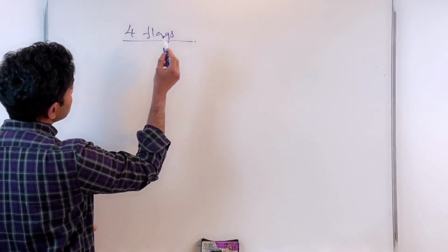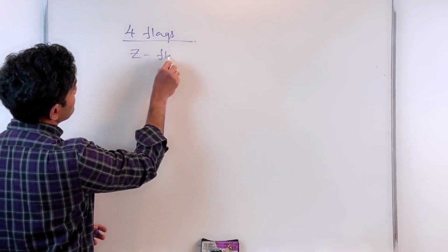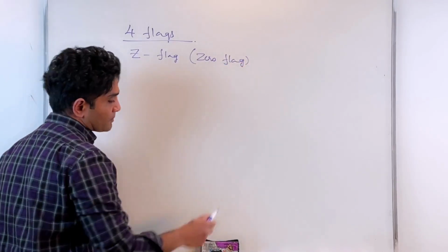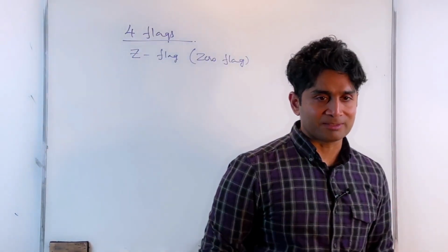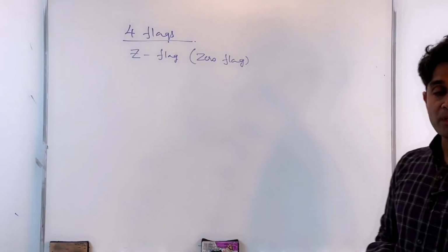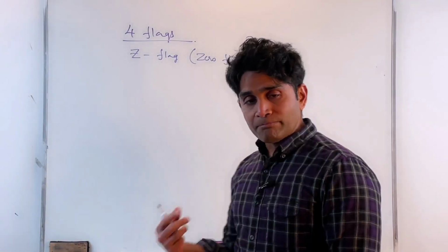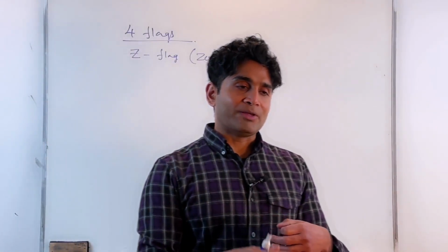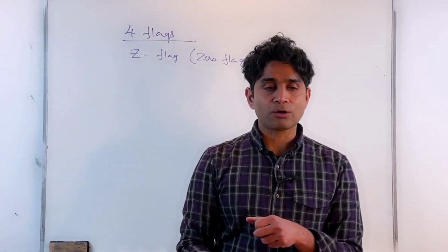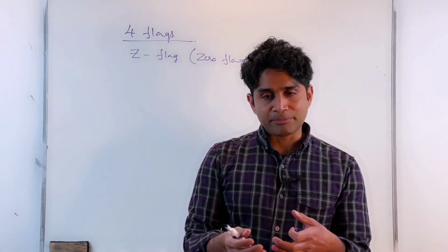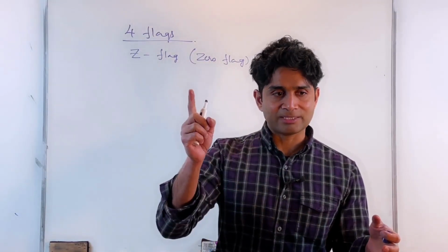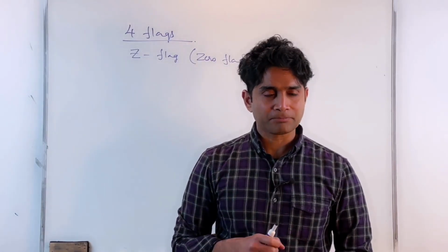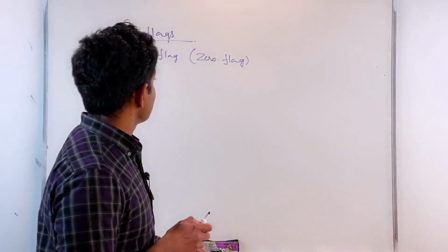We have the Z flag, that's the 0 flag. The way we have configured the Z flag, my 0 flag is true if the sum bits of my adder are all zeros, right? So it indicates whenever I have, whether it's a subtraction result or an addition operation that results in a sum being all zeros, then my Z flag is set. It's like an indicator, a flag. You're flagging an outcome. So that's how we define a Z flag.